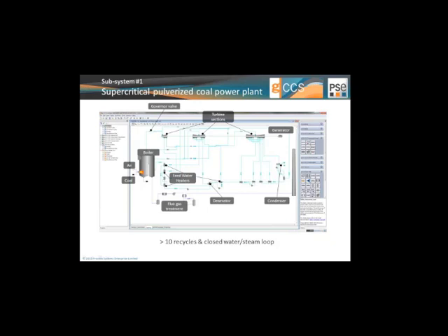This is normally a rather challenging system to converge, but I can say that the way this has been implemented, exploiting features of the gPROMS platform, we're able to converge this flow sheet from scratch by only providing initial guesses for flow and temperatures of these streams. The key here obviously is if you're modeling real assets, you will have access to the stream data and you will be able to converge the flow sheet easily.